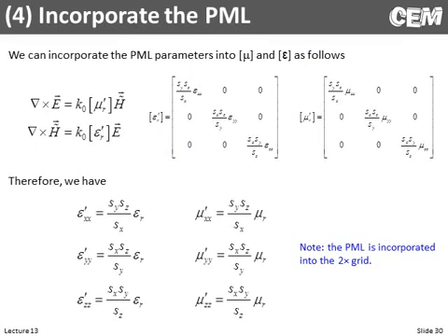Once we have our PML parameters, Sx and Sy, then we incorporate those into our material arrays. So we built our material on the grid, we calculate the PML, then we multiply these together. And what we come away with is an adjusted version of our materials that now have loss built into the boundaries. So here's how we modify all of those tensor elements with the PML parameters.